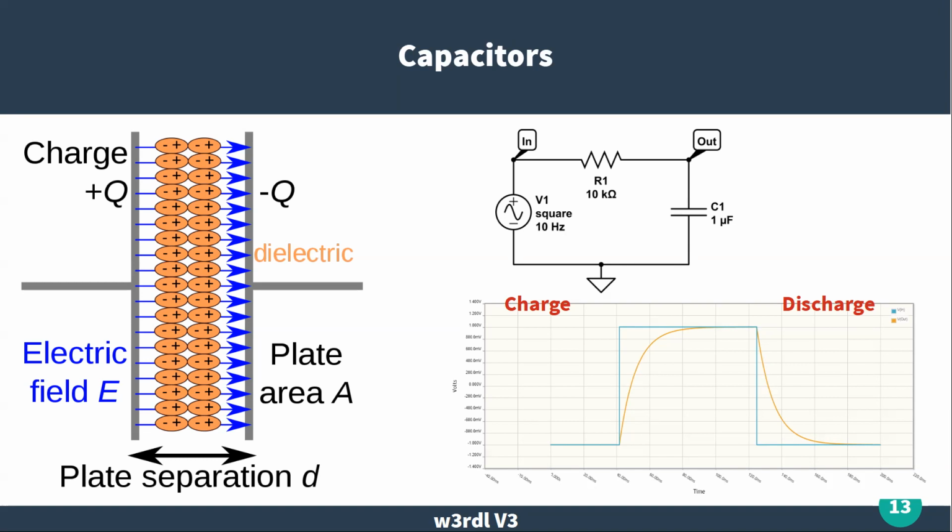So that kind of comes up later when we talk about time constants. The same thing for discharge. It works the same way. It will discharge 63 point something percent. Just think of it as 5/8. It's close enough in one time constant.